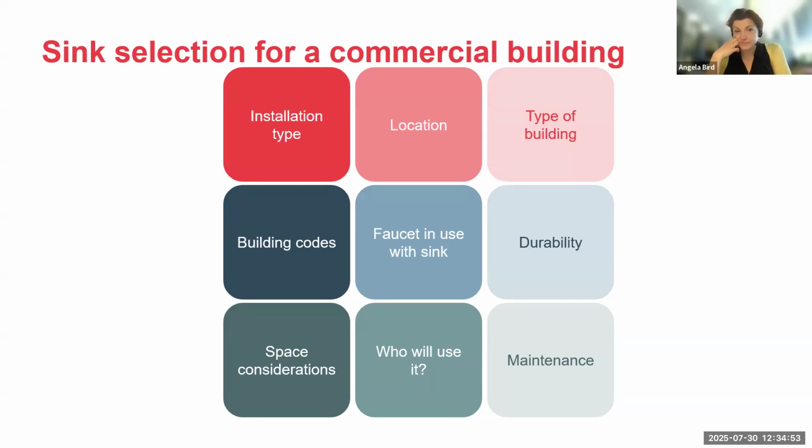And then just like 316 is better than Type 304, is a heavier gauge sink always better than a lighter gauge sink? Well, it's all application specific, right? 316 is great for certain applications, but there's a lot of places where you wouldn't want to put it because it's just more expensive. Same thing with a heavier gauge sink versus a lighter gauge sink. You've got to think of the application.